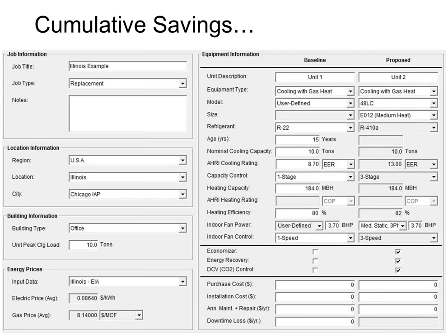So, final thoughts. I mentioned before, like with the Honeywell software, it's nice to have all the savings represented in one place, because then my savings for my DCV and my thermostat and my ERV and my staged air volume don't all add up, right? If I did calcs on each one individually and added them up, it would tell me I'm going to save 105%. Obviously, I can't save 105%, right? So I have to take into account the interaction of these different things.